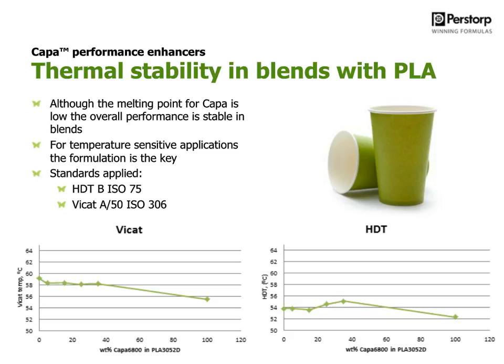And then we have evaluated them from a heat deflection temperature perspective, both using VICAT and HDT. And as you can see, even at higher addition levels such as 40%, it doesn't have a big impact on the heat deflection temperature or the VICAT, although the difference in the melting point for PLA, which is around 160, and for our product, it's 60 degrees.